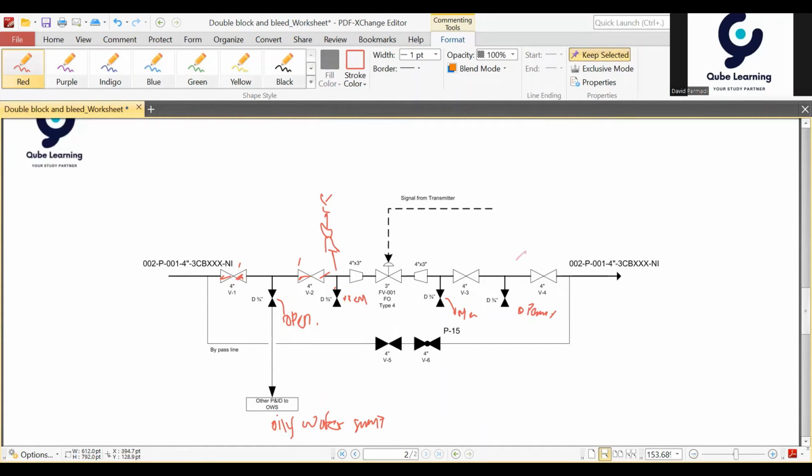During external fire, the fluid is trapped inside this line, and then maybe the pressure will go up, and then you have over pressurization between these valves, and we have no pressure safety valve, so I think you need to drain first in here because of safety reasons and environment issue.